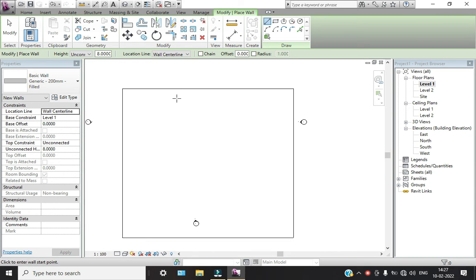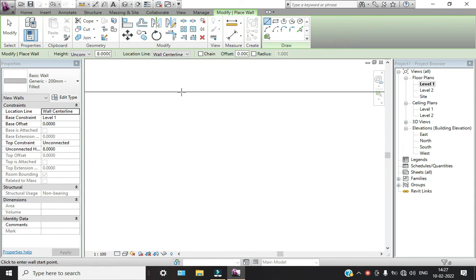we will draw our structure. So here we can see, this is the wall center line, core finish line. So if you want to start from here, so this should be selected, right? Or if you want to start with core center line, like this. So if you draw wall on wall, that will be useful, right? So we will be taking the wall center line only,